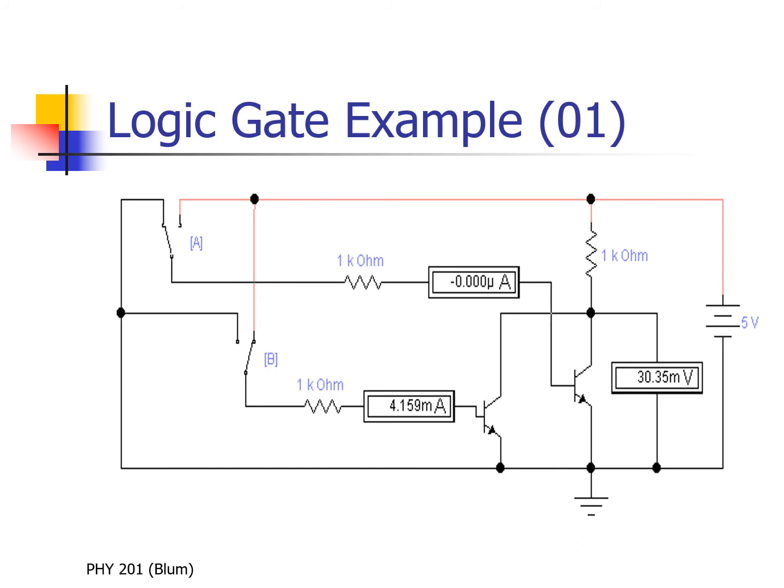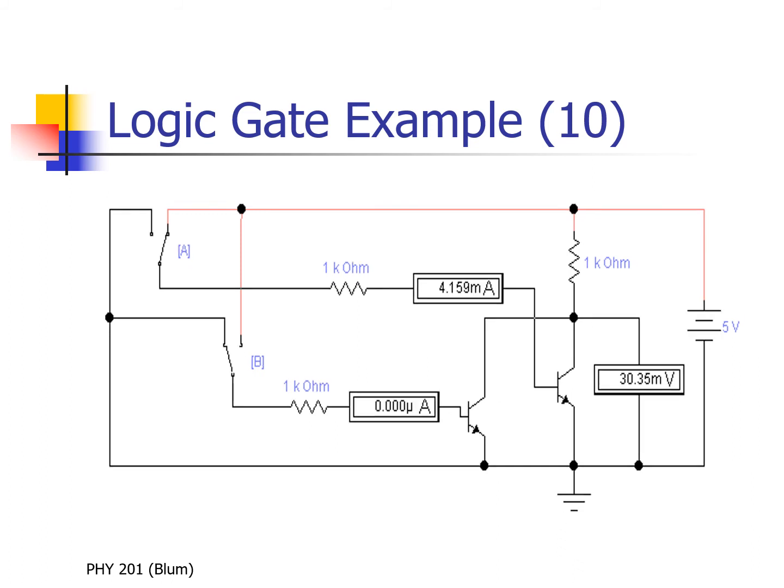That's low. This circuit is pretty much symmetric in A and B, so now we're putting in A is high and B is low, so we get pretty much the same result. So the high on A is leading to the transistor on the right turning it on, giving it an effectively low resistance.